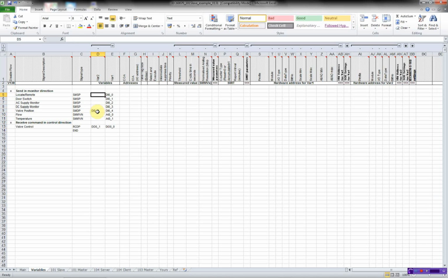Then I have my COA address. This is station 1, just like this. We have my IOA address 1. Then my time tag is 7 bytes. And then I have select execute. We can enable select execute functionality. In this case we'll just use false.